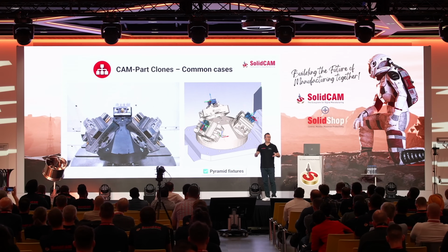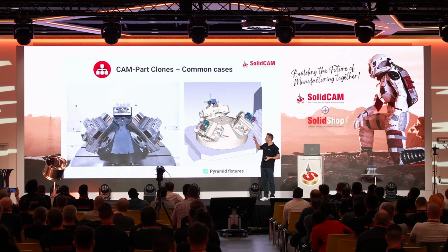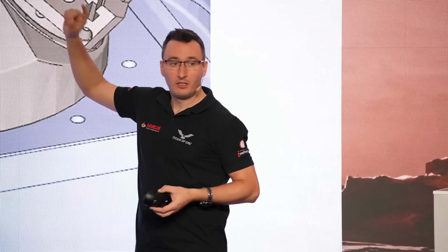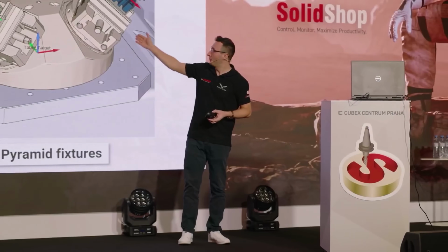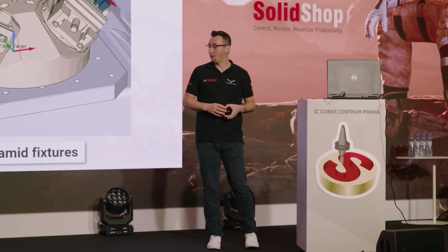There's a big deal about the work offset, how you are measuring this. Is it with a probe? Is every part the same? Do you maybe put the work offset in the middle of the fixture? So many of our customers ask, can you put the work offset on the fixture? Yes, you could, if you have a CAD model, CAD design, and then you put it there. But how to do it over here? We did that as well.